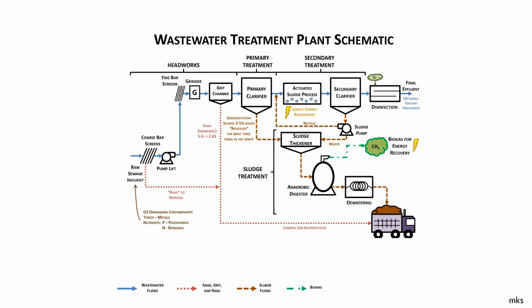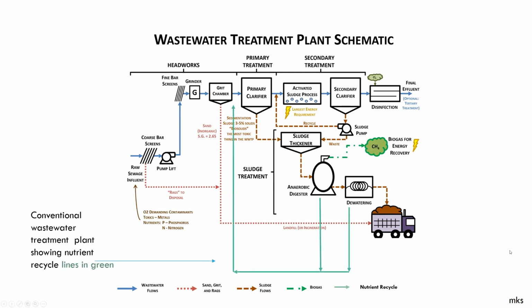So this is the treatment plant schematic, and many of you have seen this in my class. It follows the traditional scheme of treatment plants in the United States. Now in this, I'm not showing the return streams from biosolids disposal. So what we have is these recycle streams that come about from the anaerobic digester. The supernatant can have almost 1,000 milligrams per liter of ammonia. And the dewatering process will deliver additional return flows also at high ammonia concentrations and at high phosphorus concentrations. And these typically go back to the head of the plant.